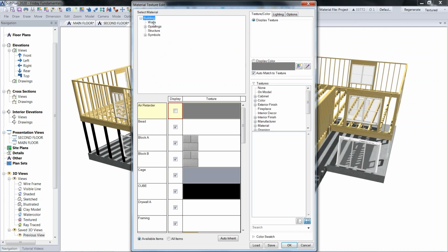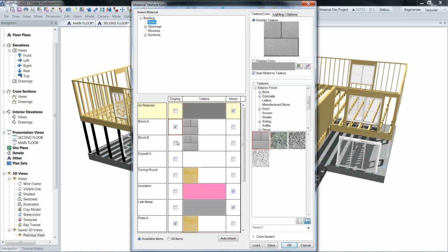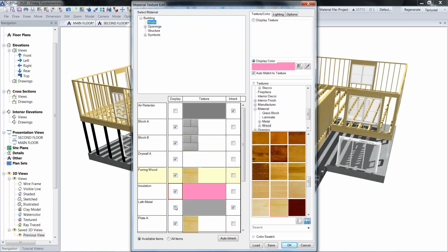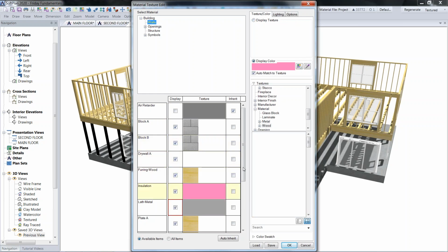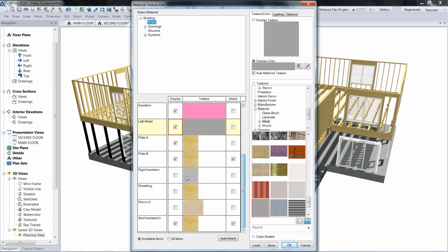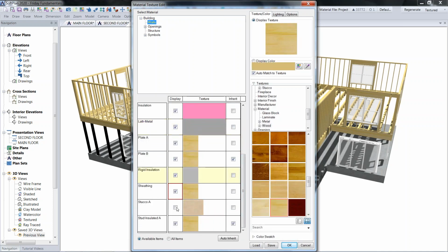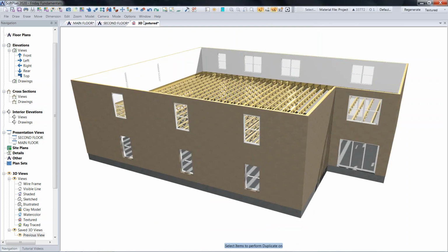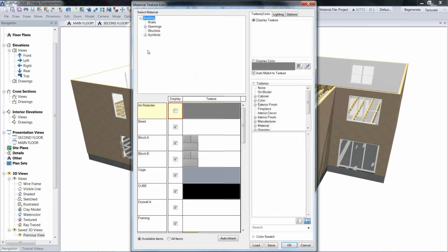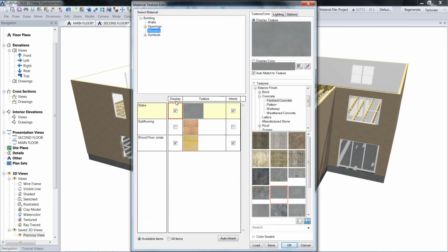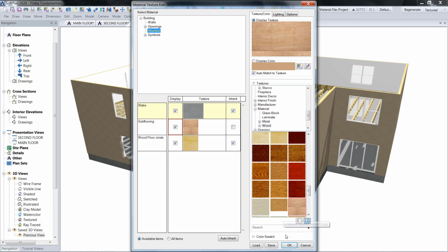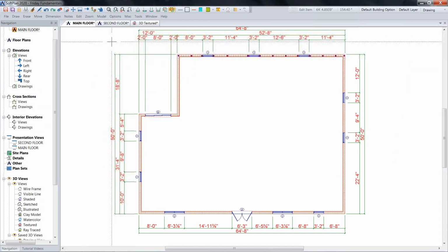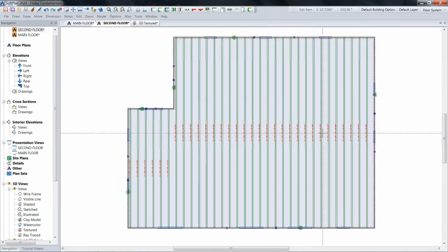Let's go to material. Let's go back into walls. Let's say, okay, turn on your blocks, turn on your drywall. I don't care about that. Insulation, okay, fine. Lath, wrapping, you'll need to see that later when we do bill of materials takeoff. Rigid, sure. Sheathing, yep. Stucco, okay, done. And we are back to this. And then structurally, we need to go to options for our material and say, okay, for the structure, turn on the subfloor. Okay, done. All right, there. Good. Let's go back into the main floor. That's set up. Second floor is finished. Everything is in place.